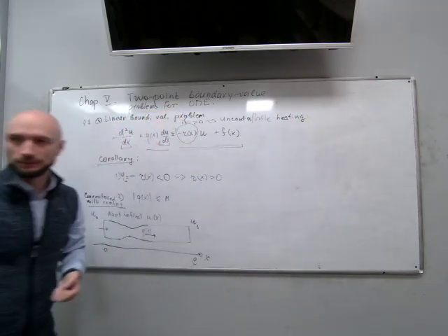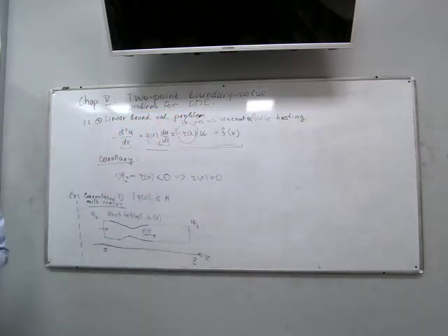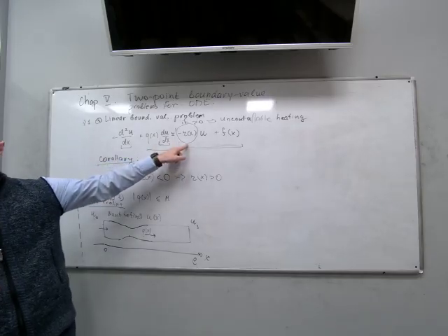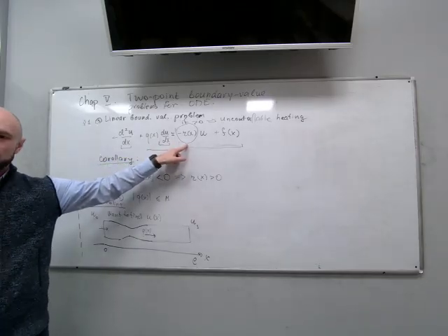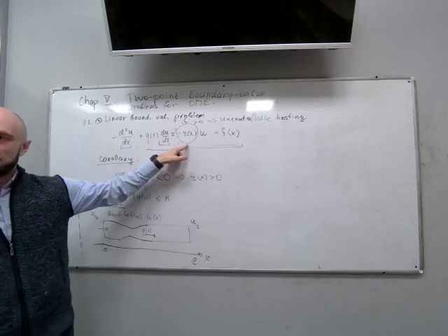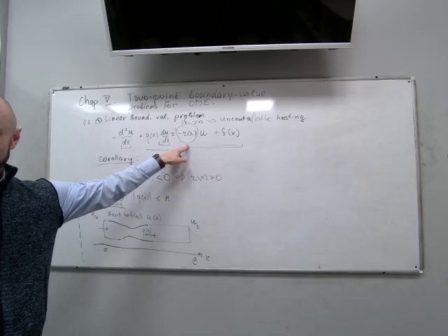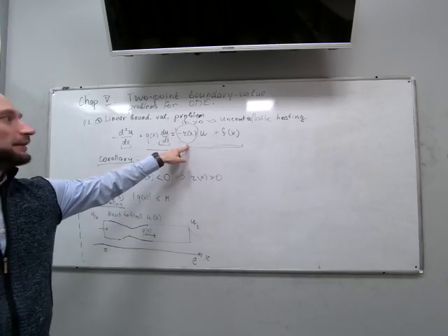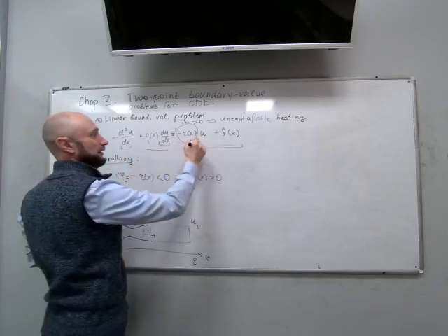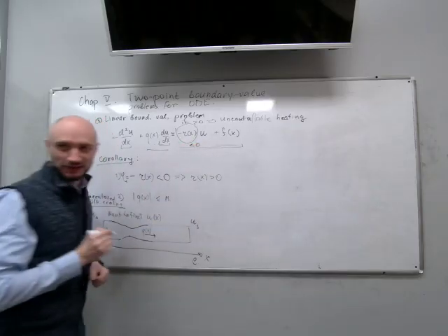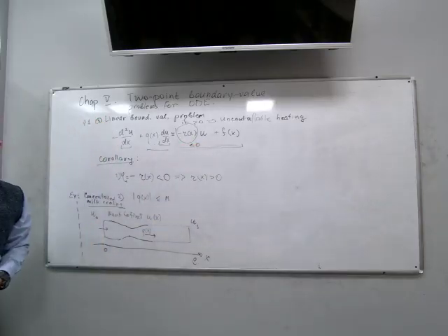You see it or feel it? Yes. If we have a positive value of this coefficient, then we'll have an uncontrollable heating, which is bad and mathematically complicated. That's why we require that this whole term is negative to prevent uncontrollable heating, meaning the higher the temperature, the smaller the contribution from this temperature-dependent heat source.